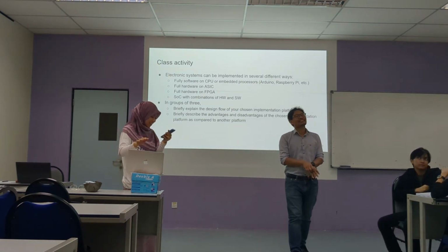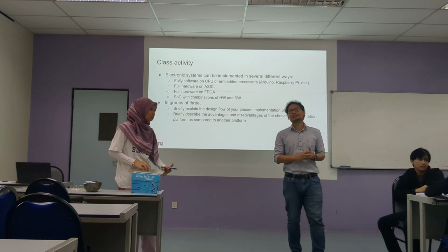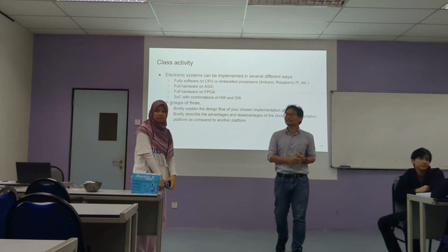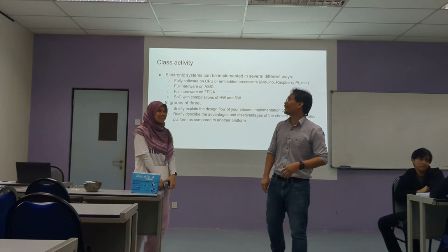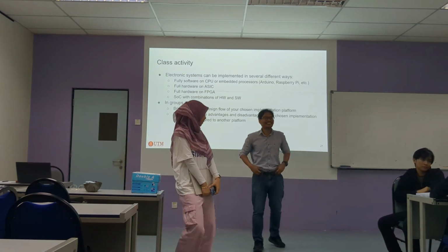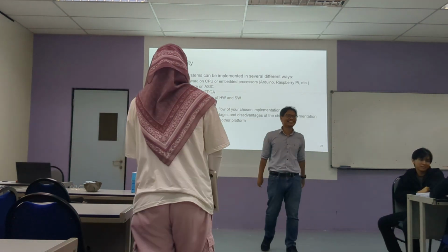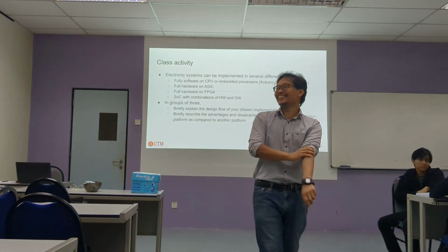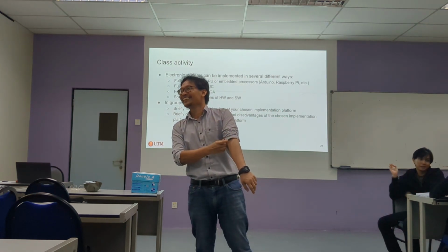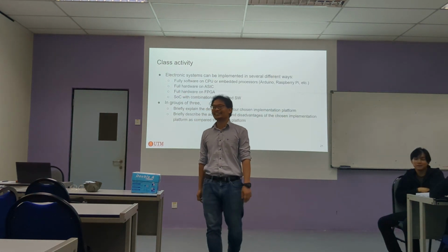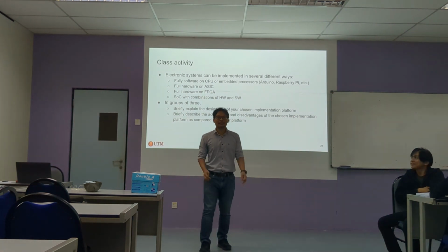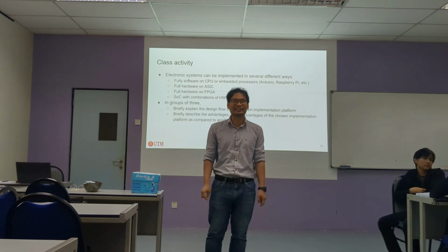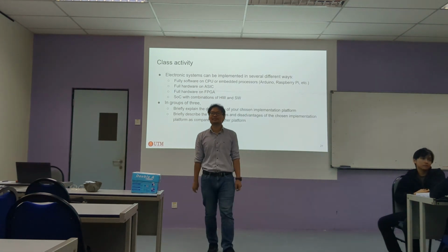I would say limited stability. I mean, the design can be stable for both. What do you mean by stability? Scalability, yeah, okay, scalability, correct. But stability, I think both should be stable. Right. Okay, so what does it mean by scalability? Limited performance and power. Okay, correct. In terms of scale, because you have all the other components inside the FPGA, right? ASIC, they're custom, right? You just go fully custom.